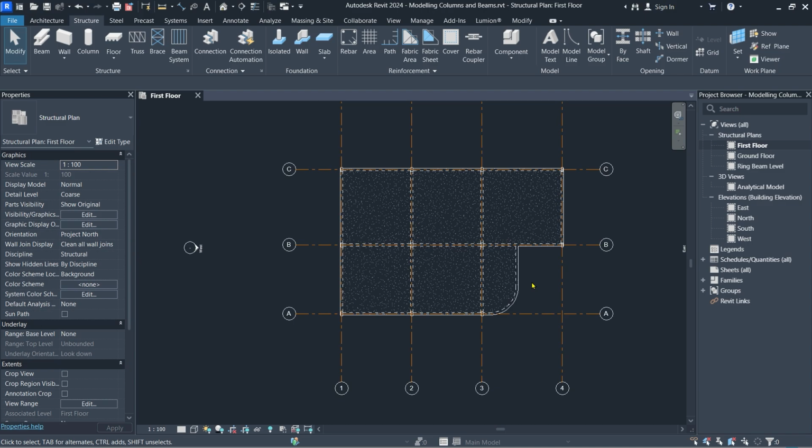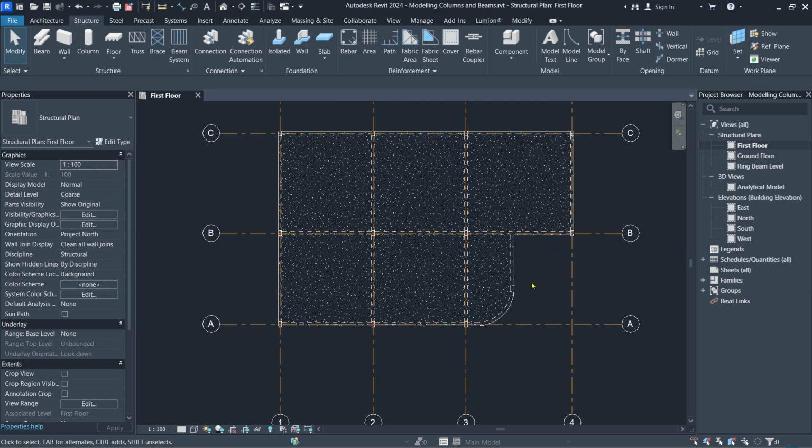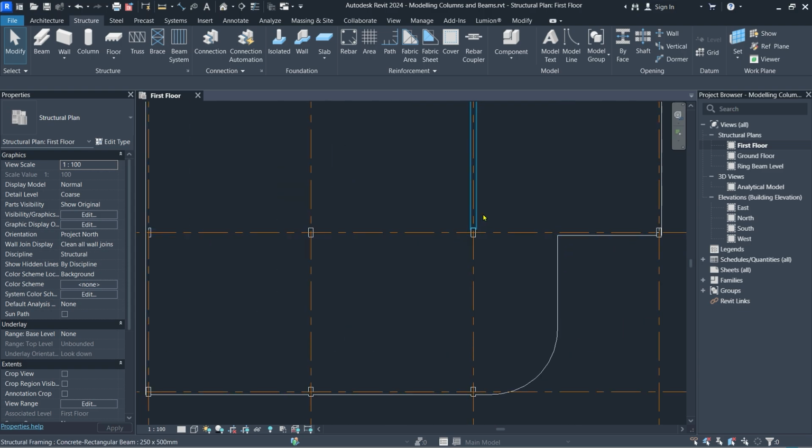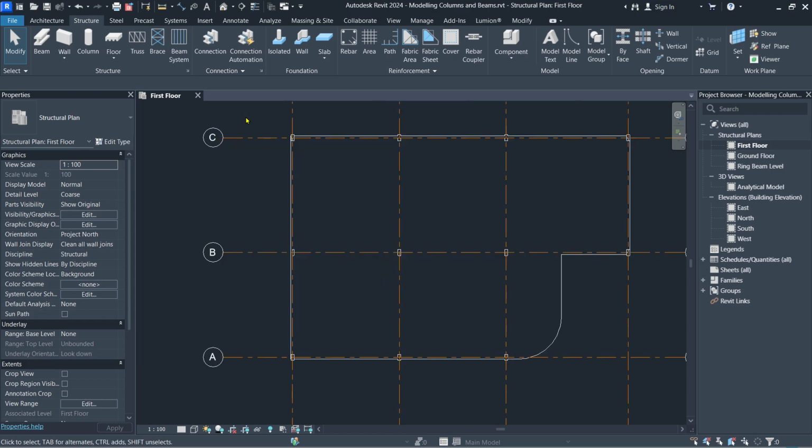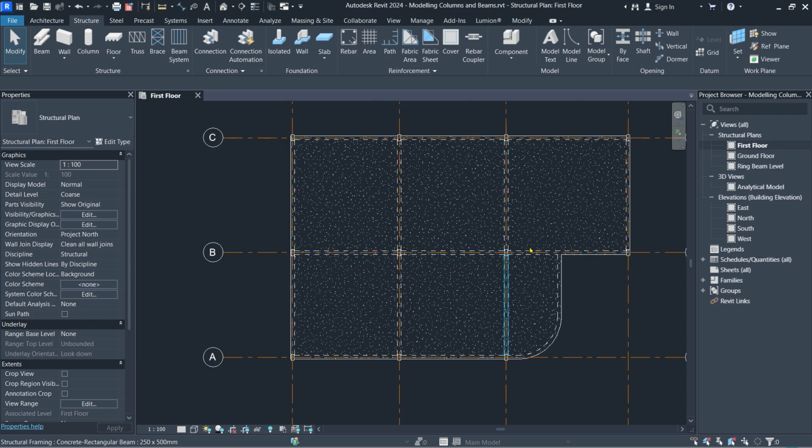Flat slab systems are, in simple terms, structural systems where you don't find beams. So the slabs sit directly onto the columns. However, at these joints where we have the intersection, there is a phenomenon called punching shear that happens around here. To counteract that, we normally deepen the slab at this point, of course with punching shear reinforcement.